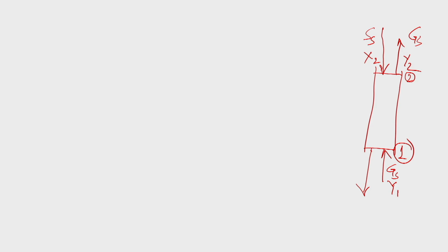Whenever it will be leaving the chamber, then we can say this dry wet flow rate is Ss with this solute concentration of x1. Let us take one differential thickness of, say, dz, because we assume that this z direction will be from point 1 to point 2 like this. So dz will be there, and through this both the liquid flow rate and gas flow rate, or the adsorbate flow rate and the adsorbent flow rate, will be there.